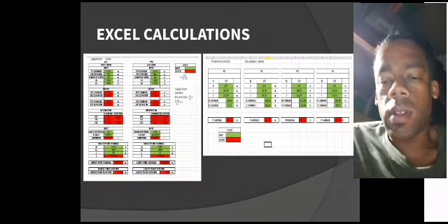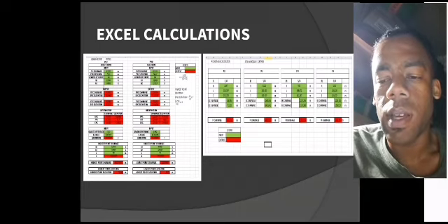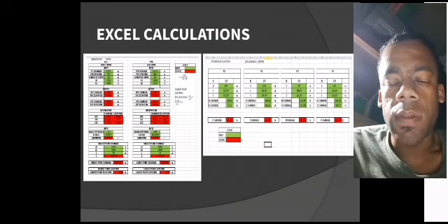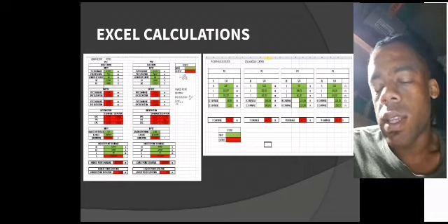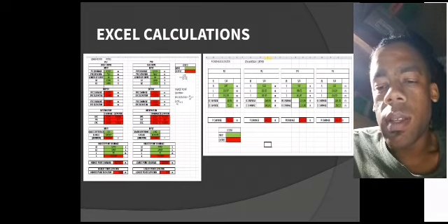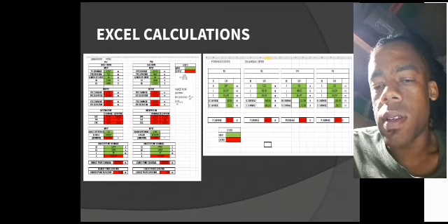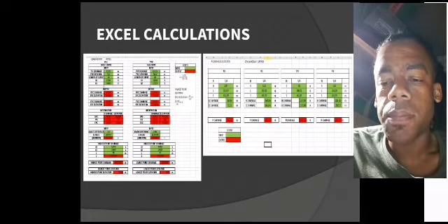This is the Excel calculation I've come up with. I first did the manual calculation, taking the results that were generated by Civil Designer with regards to the horizontal and vertical curve information, and I did one, and then I was able to just duplicate the functions of finding what is needed when it comes to the horizontal and vertical curves.